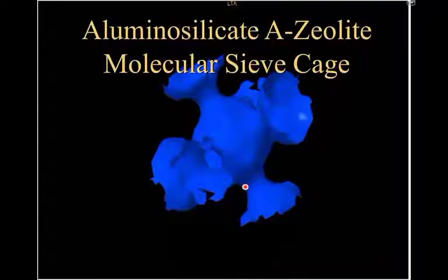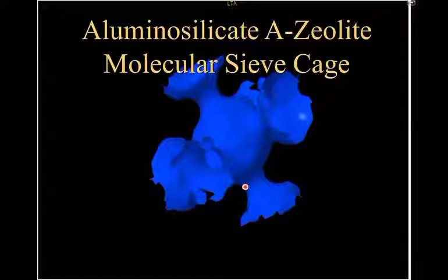You really need the interactions with the walls to cause strong enough forces to retain the material by physisorption, but weak enough forces that you can regenerate easily with a drop in concentration or a drop in pressure, namely pressure swing. Sometimes you might have to use thermal swing.